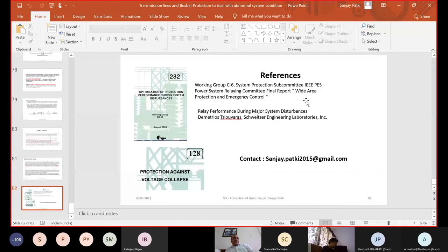will actually cause further damage to the tank, or even sometimes tank rupture, which is a cause of fire in many cases. Most of the cases, the fire can be prevented if we can prevent the rupture of the tank at some location. And because the oxygen requirement for the faulty condition, where the high temperatures are there, is available only when there is a rupture taking place, no delay should be provided externally.